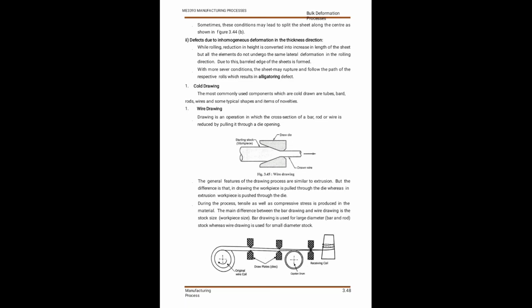A rod is formed into a wire in the wire drawing process. A number of stages of drawing plates are mounted and a pulling force is applied to reduce the cross section and increase the length, and the diameter is reduced from around 15 mm to 1.5 mm.